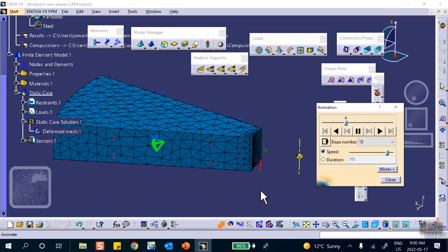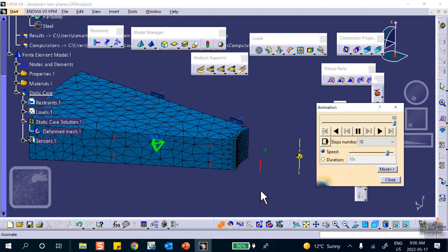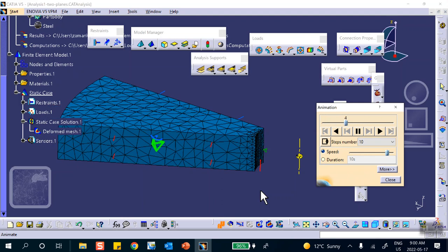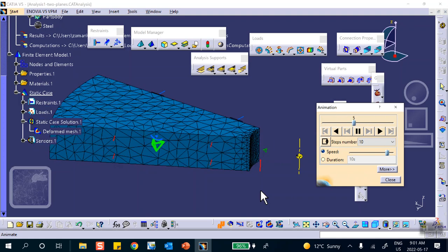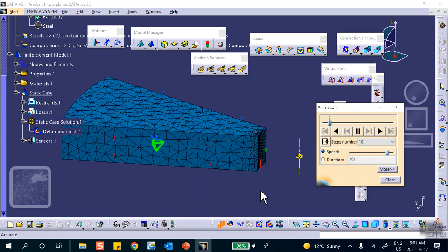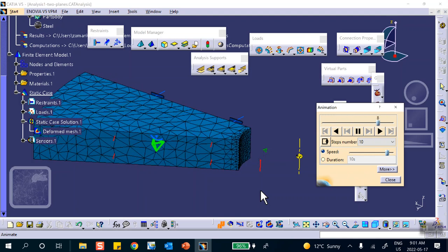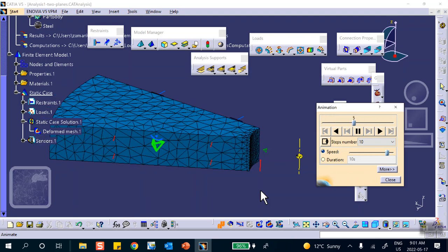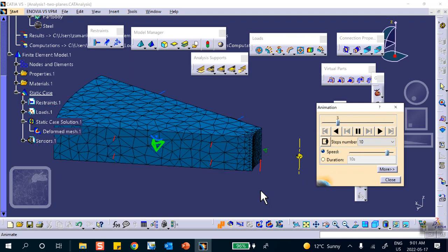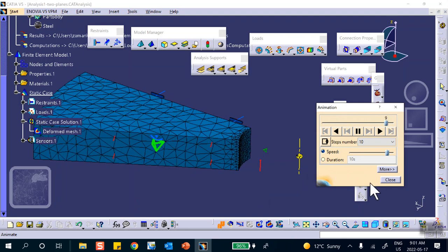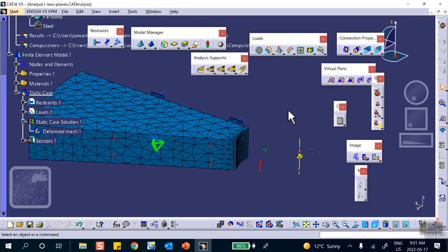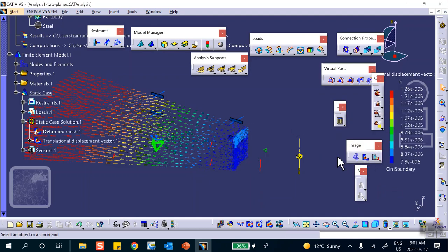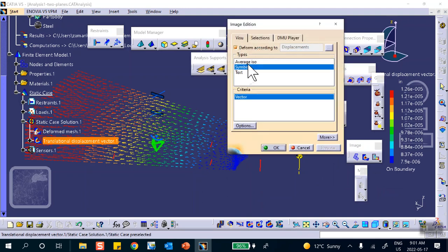Okay? Now, it is not quite clear here. We got to look at it more carefully. It looks like what it's supposed to. This disk is rotating. It goes out. It looks like that, but there's something that's bothering me right now. I'm not sure. Let's look at the contours of displacement, for example. They better be rings. They all go the same way. They better be rings. This is kind of tilting. I don't like that. We'll find out what's going on. Okay, so maybe not.